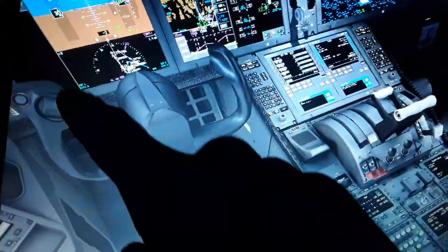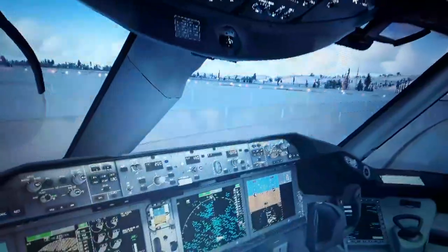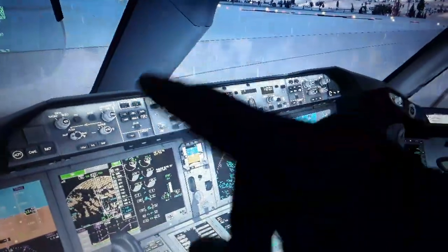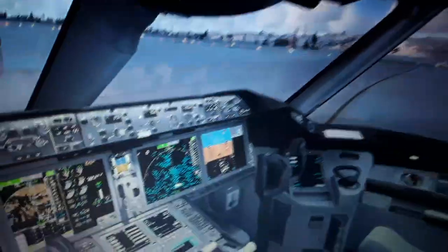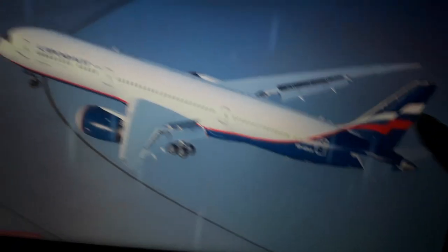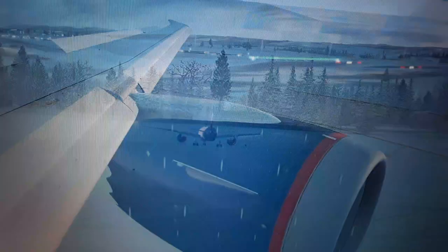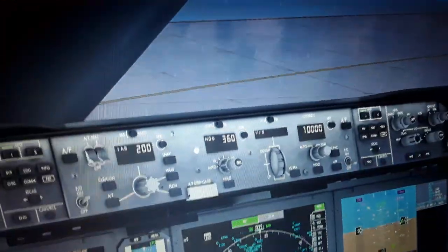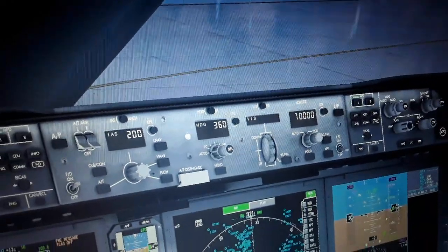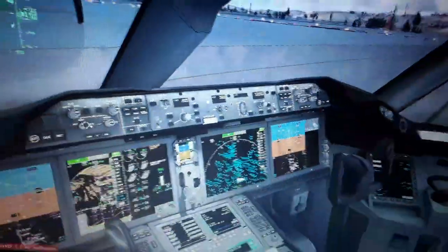So this also disconnects from the autopilot and flight director system panel the auto trim function of the horizontal tail of the aircraft. So if we have a failure of the hydraulics L1 and R2 over here, the auto trim function, because we have also automatic trim from the autopilot and the auto throttle switch.